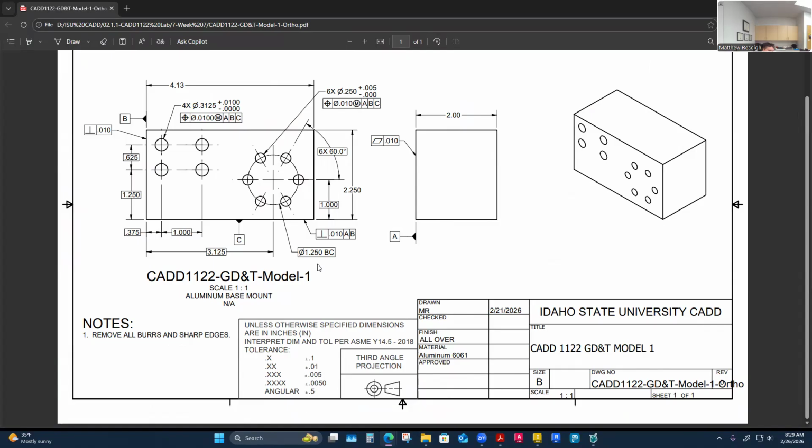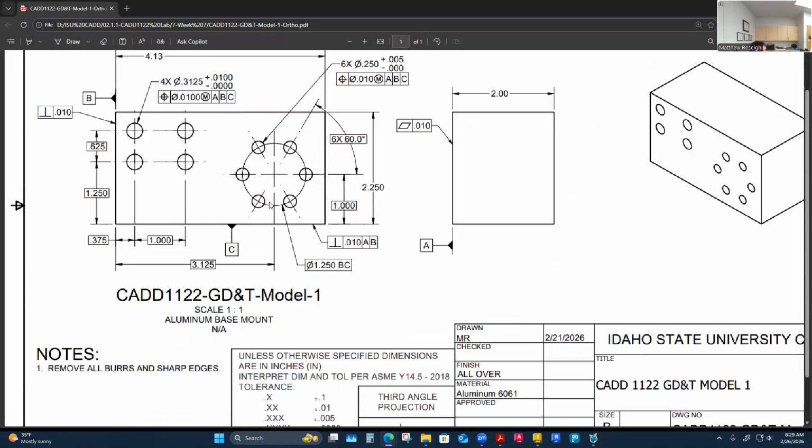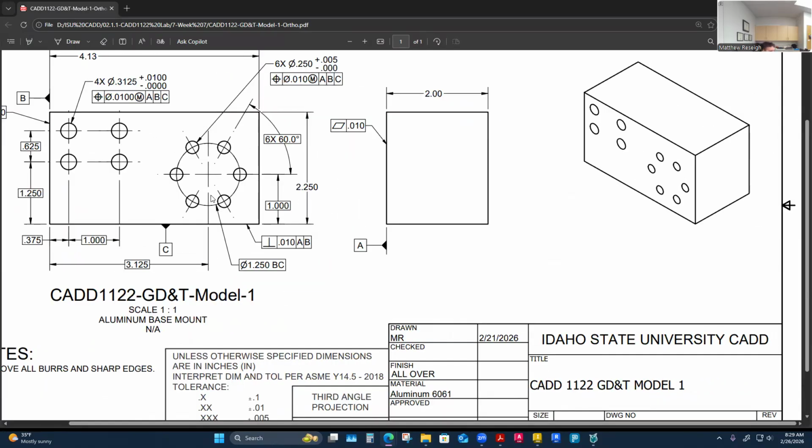I'm going to establish my bolt circle, and I'm going to establish one of these holes that's probably on a quadrant. This is how I look at circles when I go to draw them: looking for a hole to start with that may start on either the horizontal or vertical center line. That's why I would start with this hole and pattern it around from there rather than try to lay this out. I could figure it out. There's 60 degrees between them, so it's only 30 degrees off of this. That would be fine. Just generally, when I look at a round set of features, I might look to locate the one that's clocked at a 12, 9, 3, or 6 o'clock position and then work from there.